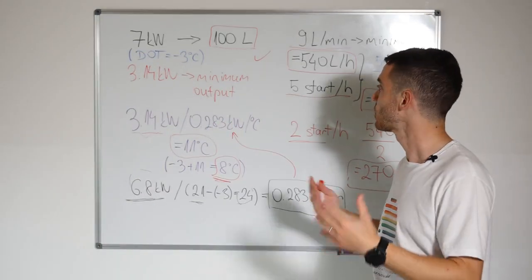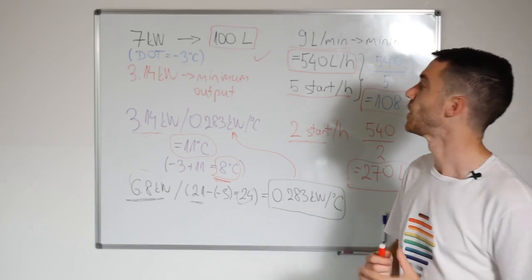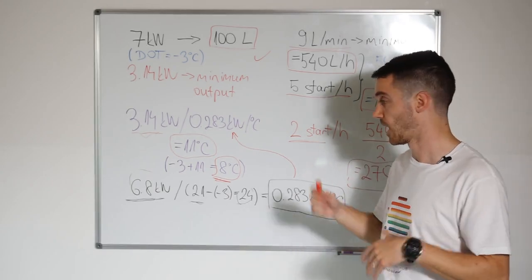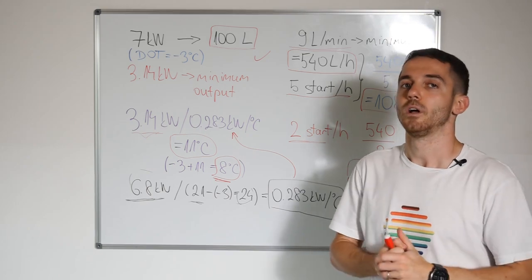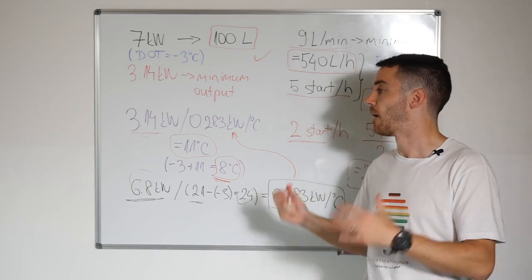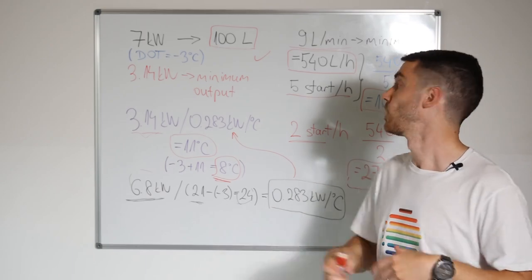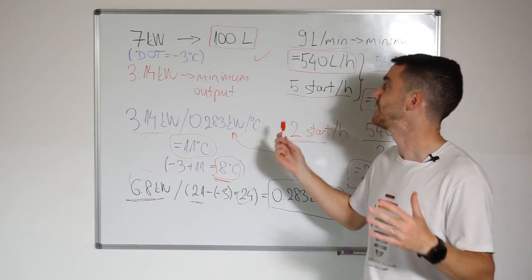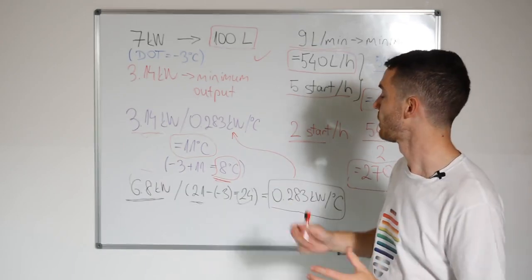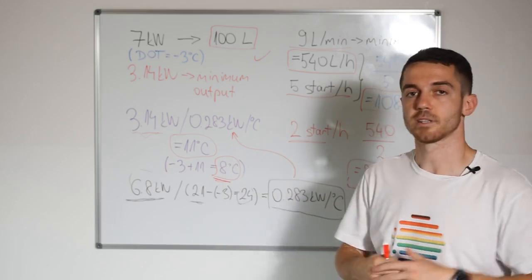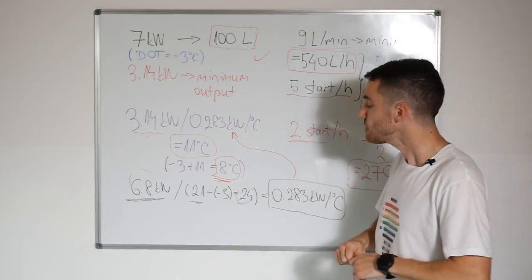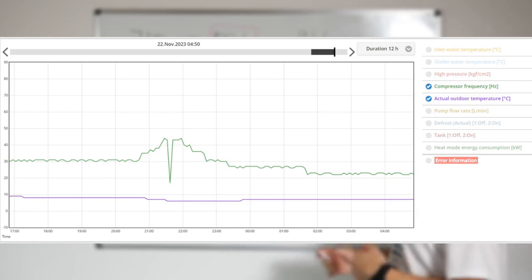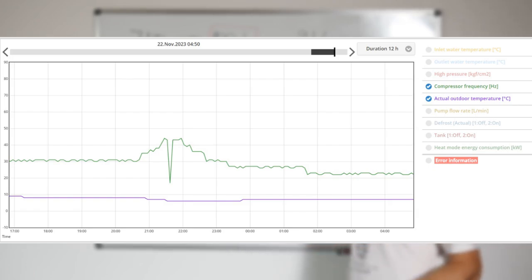The calculation is much more complicated, and usually you cannot calculate this exactly. It depends on the algorithm, on how the compressor and pump are modulating, and on the minimum output. So this is only one case, with some heat loss and some design outdoor temperature. We can see here that we need to ensure modulation and we need to ensure volume.